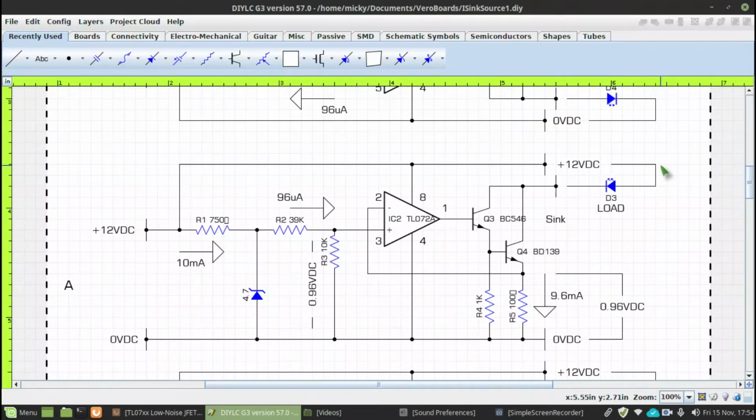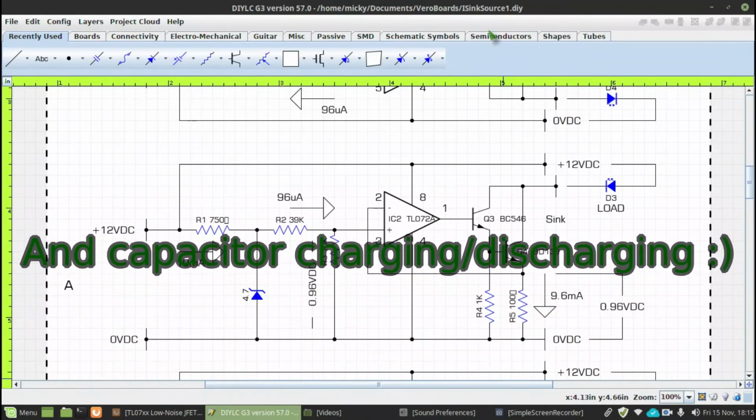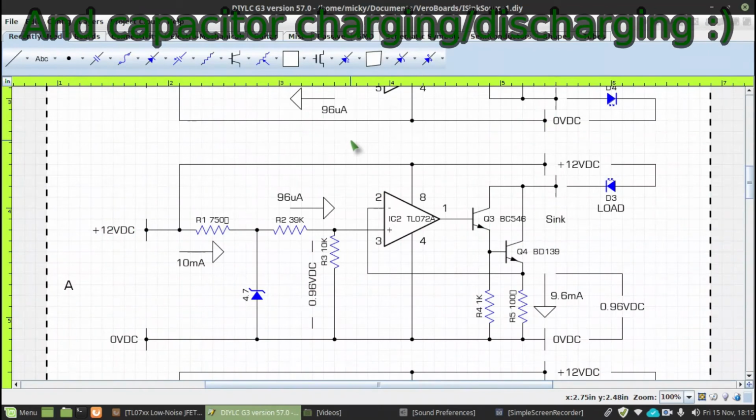I'll mention one here, which is a temperature device. If you have a constant current and you feed that into a resistive sensor, the temperature then becomes proportionate to the voltage across that sensor. That was just a small sample of the many uses, applications that you can put a constant current source to.